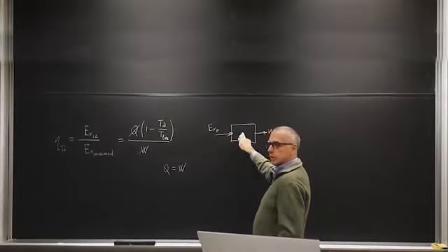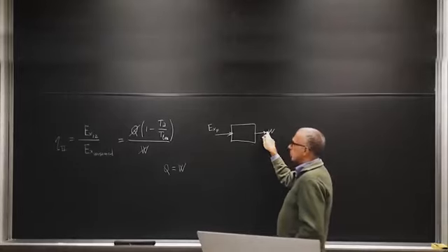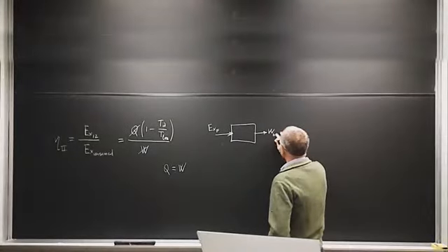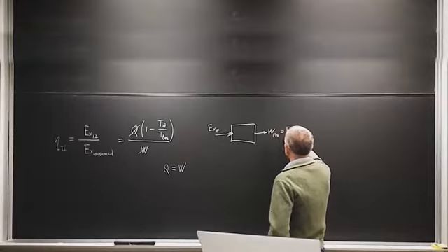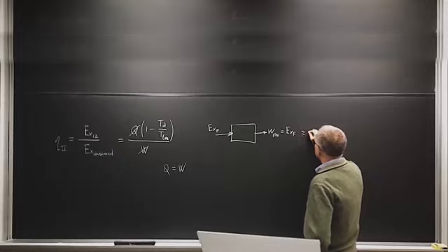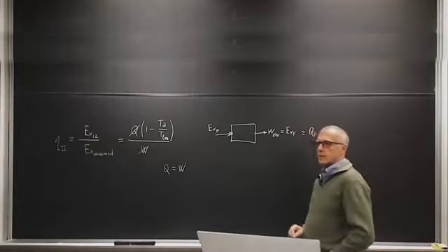There is no loss of exergy, so the exergy of the fuel goes all into exergy of the product. So it's 1-to-1. So W max, or let's say W rev, is equal to the exergy of the fuel. But the exergy of the fuel, we said, is approximately equal to the heating value. Let's call it QF to simplify.